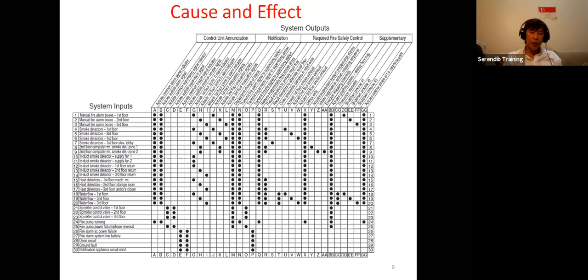Then you configure whether the detector activation will be silent or it will evacuate the building. It's up to you. But if you go with NFPA, building evacuation is not required for an activation of smoke duct detector. I hope that addresses your question.